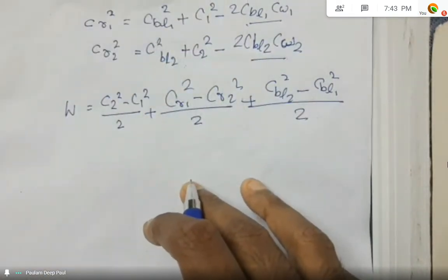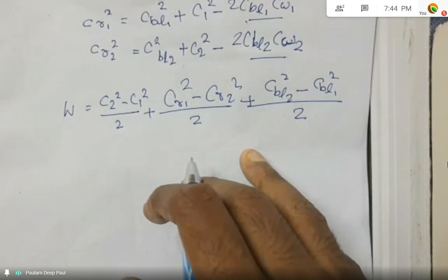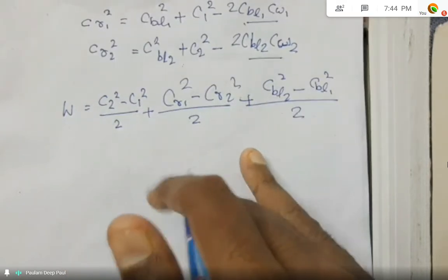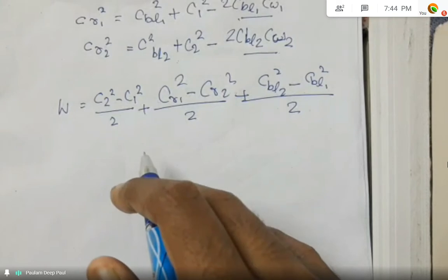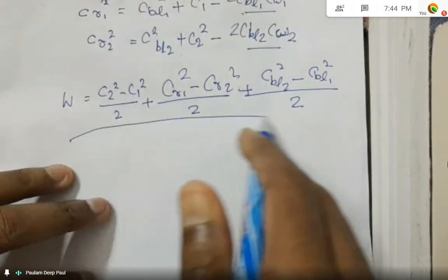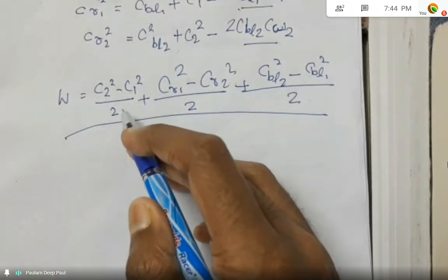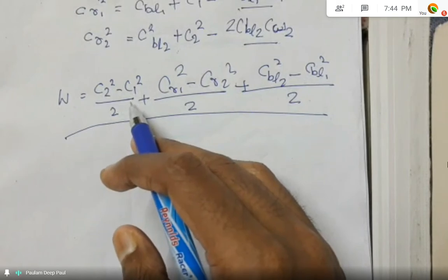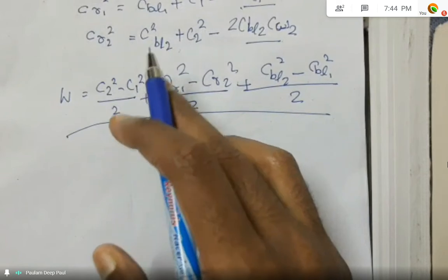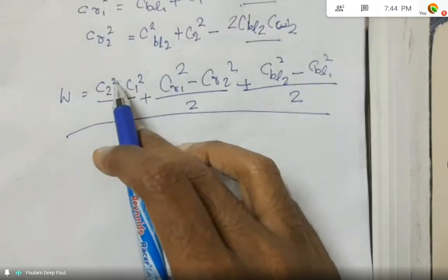You can express it for compressors, centrifugal pumps, axial compressors, axial pumps, and everything that takes in the centrifugal effect. You can just denote it from Euler's equation, that is Euler's work. The first term, C2 square minus C1 square upon 2, shows the increase in the kinetic energy of the working fluid in the impeller that has to be converted to pressure energy in the diffuser.